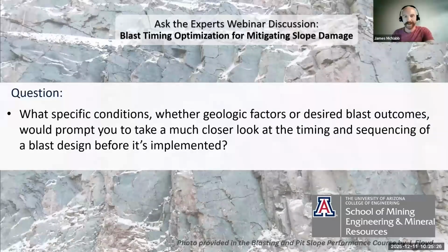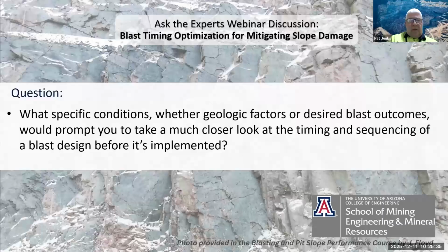Excellent. Would anybody else like to jump in on that one? Well, I'd just like to add that this question, I think, highlights the importance of having good performance data, good seismographic data so that you can address some of those questions that Paul raised. Understanding where those blast timing domains fall with respect to the geology, I think, is going to be critical to you, and that's why it's important to have that good seismograph data, good signature hole data from which to base good timing. And at the end of the day, you may not shoot through all of those different zones.